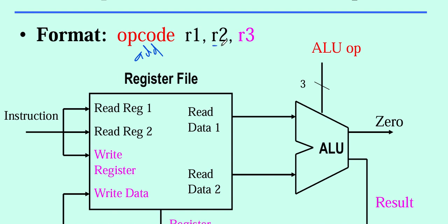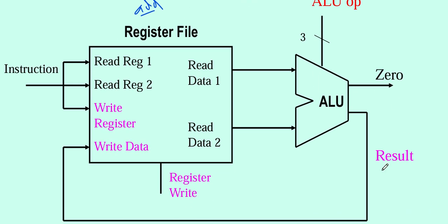It means our operands are what? R2 and R3, right? So yeah, we need the register file to fetch R2 and R3. Now we need add to select the correct ALU operation. Then we need R1 as our destination register because we'll be writing the results back to our register file. So you realize that once you conceptualize these things, once you know what they do, automatically you know the hardware they involve. So that's the importance of knowing the instructions and knowing the type.